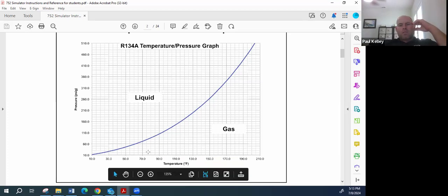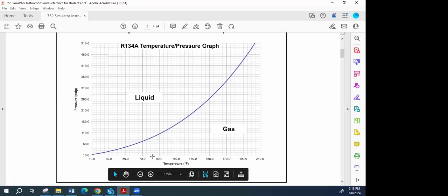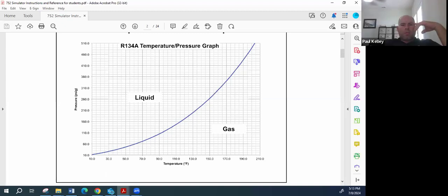So let's say, what temperature do you guys think it would be at the school right now? We're not there, so we could guess. Like 80 degrees. All right, so if it was 80, would you agree it would be right about here? I'm going to go ahead and do a quick annotate. If we're about 80, we'd be right about here. Run that up. Once that hits this line, then you come over like this. Then if you figure out where this should be, like this is probably 65, 77, 80, 85. No, this would be 70, this would be 80, this would be about 90. So at 80 degrees, it should be 90 PSI.